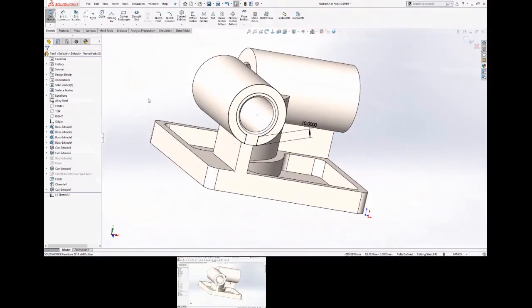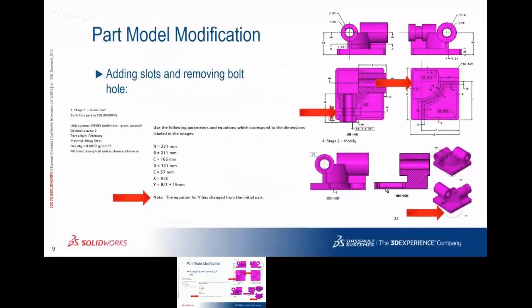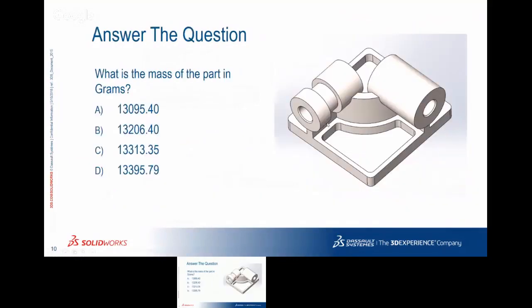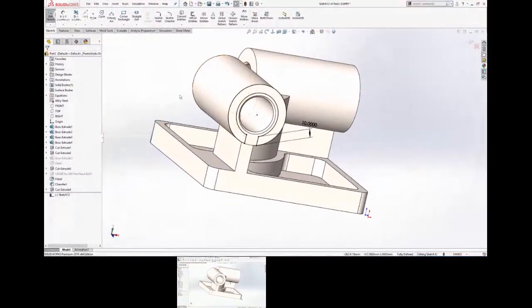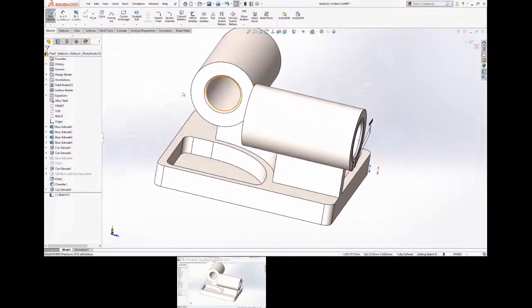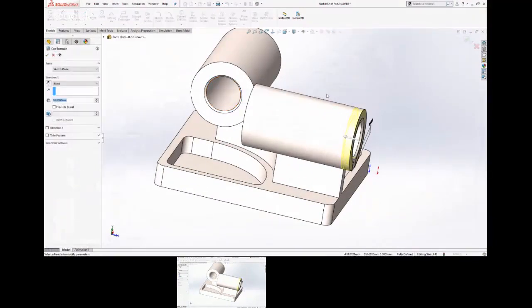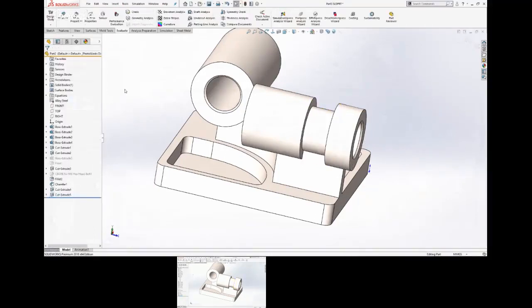Anyway, so again, let's go back and we'll look at the drawing, see how this has to be created. This arrow is right in the way, but it's basically 30 millimeters from this face, and then it's 30 millimeters deep. So we'll grab the extruded cut tool. It's just going to be an offset. I'm still kind of bewildered why it's not giving me a contour. So offset, change the direction up here. Sorry, getting some buzzing. And then this is going to be 30. Okay, and there's my cut.